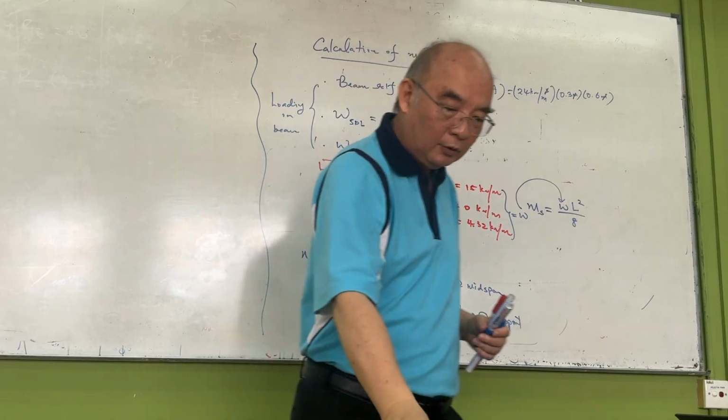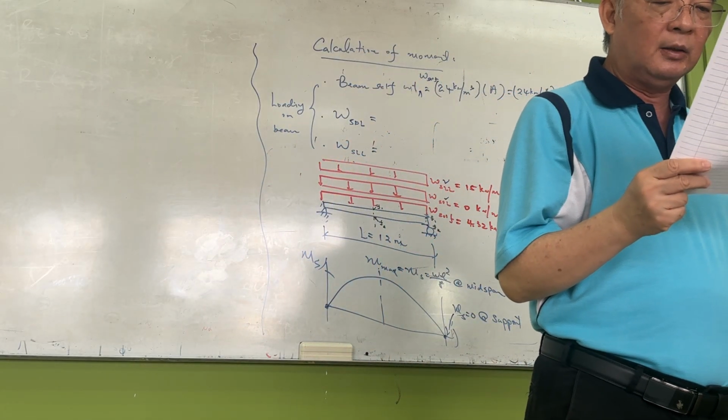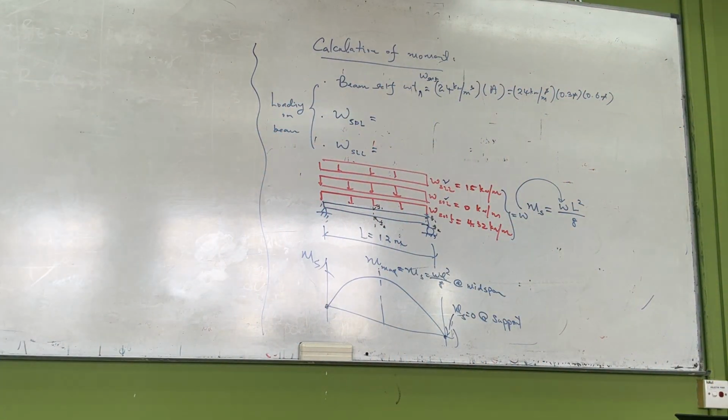If you look at the first question, it is to compute the extreme fiber stresses at midspan and support at transfer condition. So normally part A is at the transfer stage, and normally part B will be at the service load stage.